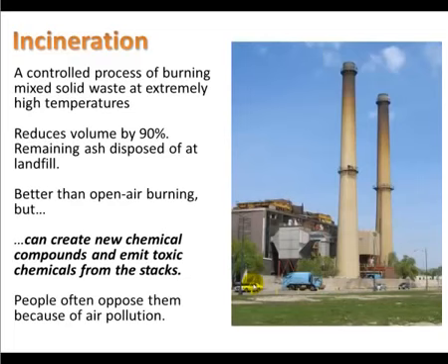So another option besides burying it is to burn it, and that's incineration. This can reduce the volume by 90%. You still have 10% of it left behind as ash, and that ash you can put in a landfill. It's a pretty controlled burn, and the smokestacks have some filters on them, so it's better than just open air burning. But it can still create new chemical compounds and emit toxic chemicals from the stacks.